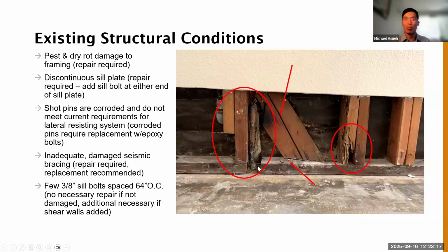And you have sill plates that are discontinuous. Basically, with items like this, in some ways the project team was like, you almost wish that you wouldn't see it, right? But you can't ignore it, and you have to assume that you need to have a plan to be able to treat these things. And so that was a part of the project that we did, just repairing and making sure that they're at minimum up to what they were supposed to be when they were first constructed.